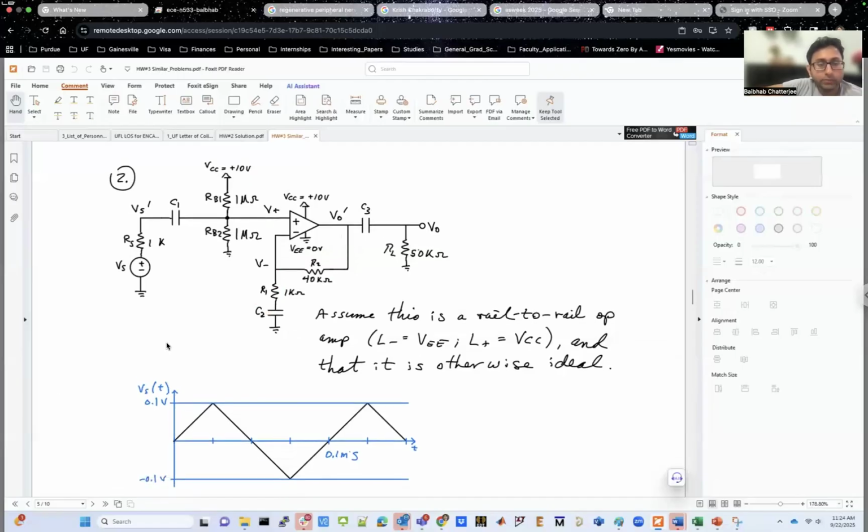Okay. So in terms of AC, whenever you need to do any kind of AC analysis, ignore what has been done for DC. So what has been done for DC in this case? Of course, you have these DC blocking capacitors. For AC, this capacitor will be shorted. So you have shorted capacitors. These are just creating the DC biasing point. So these are also not important for your AC analysis. So you can get rid of them. This capacitor over here also becomes a short for your AC analysis. So just make it a short. This capacitor over here becomes a short for your AC analysis.